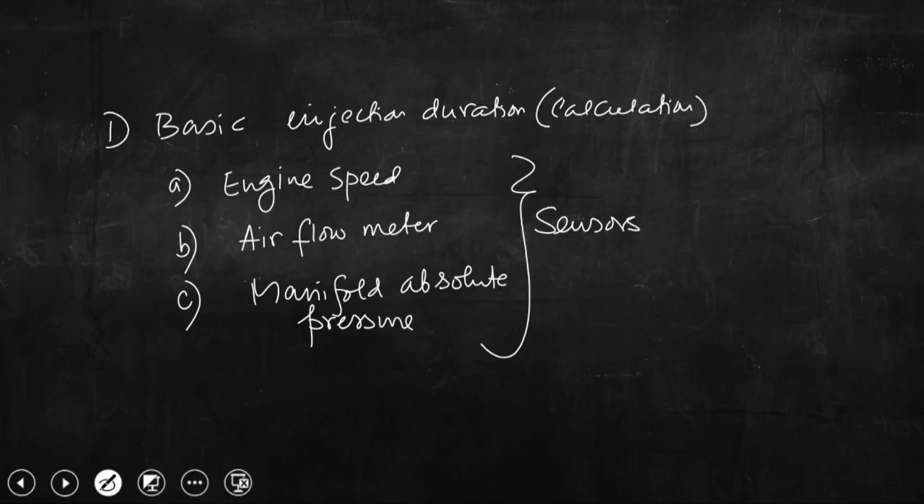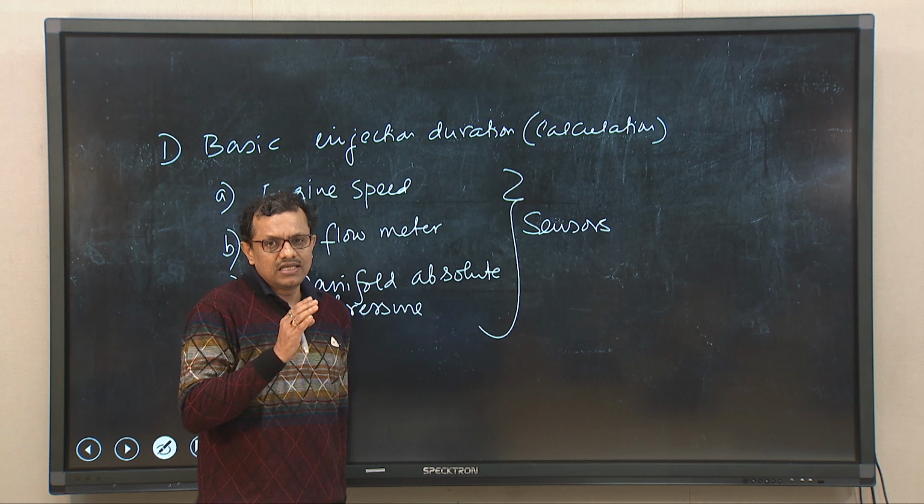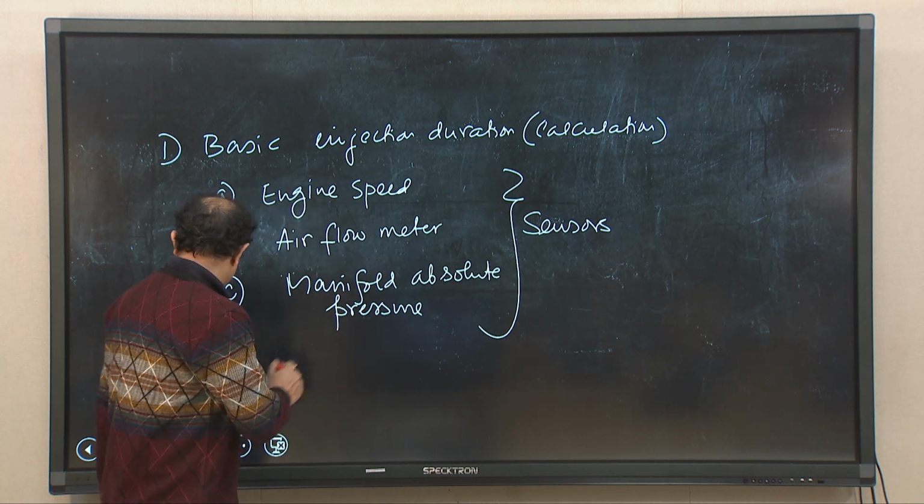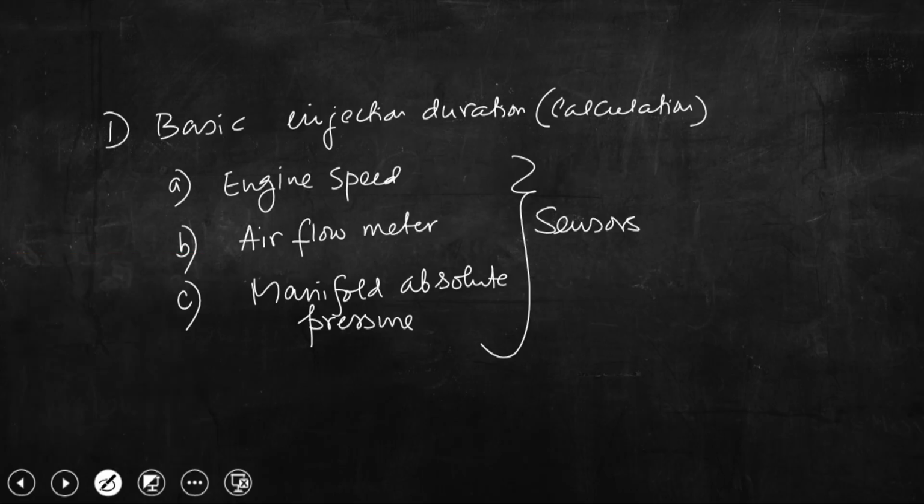These two quantities are very important. So, let me repeat once again, basic injection duration calculation is based on the engine speed and airflow volume.